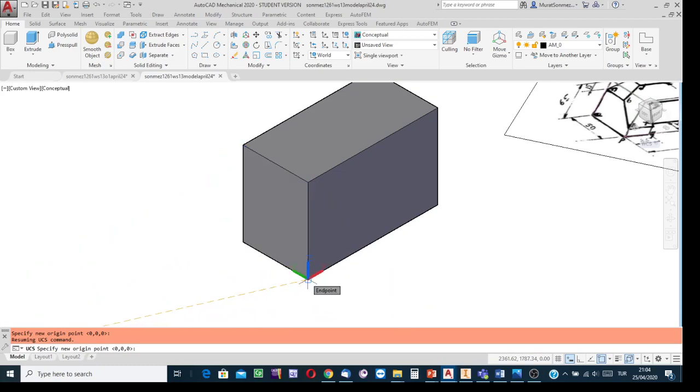Okay, this is the first point. It is to indicate the origin. And then say that the x-axis is to extend in this direction. If I show a characteristic point, thanks to snap enabling, of course, at this corner, I can say that the x-axis passes through this point to its positive side. Okay, and then indicate this corner, snapping, to say that it is one of the points along which the y-axis passes through.